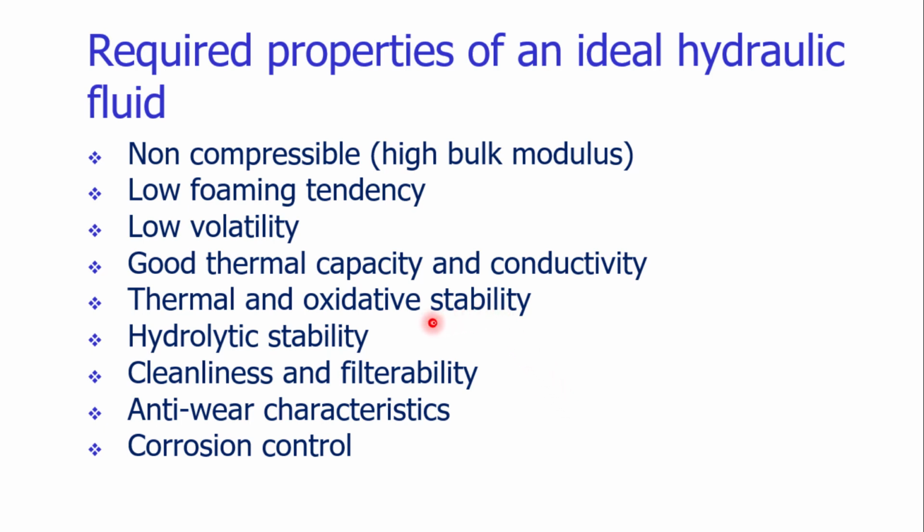The hydraulic fluid should have sufficient thermal and oxidative stability. The fluid should be stable enough. It should have the hydrolytic stability as well. The fluid must be clean, and it can be easily filtered. The hydraulic fluid should provide the anti-wear characteristic. It should provide good lubricating characteristic.